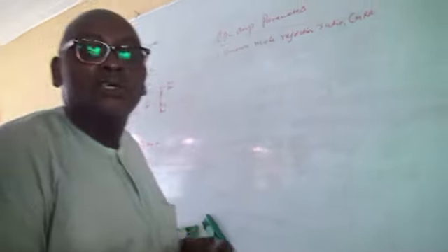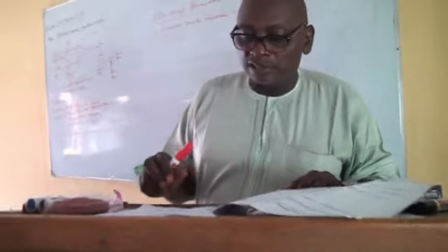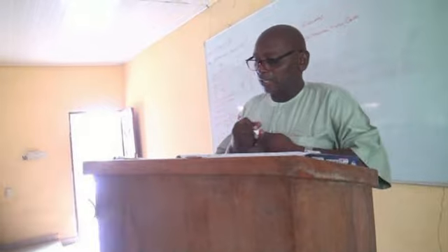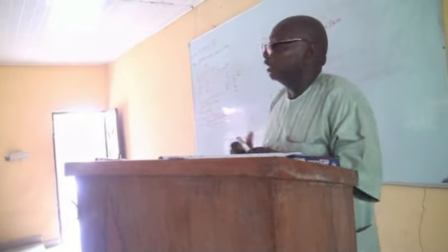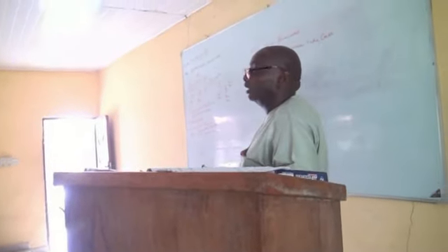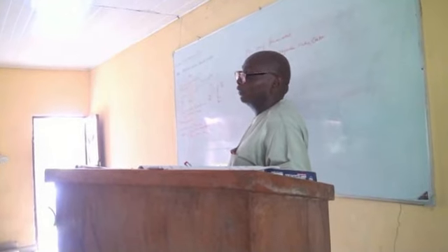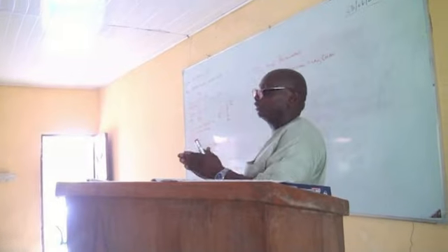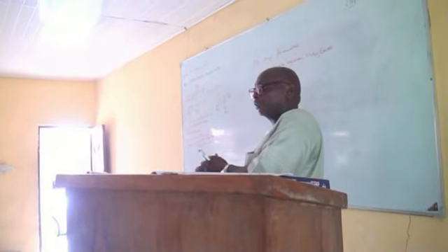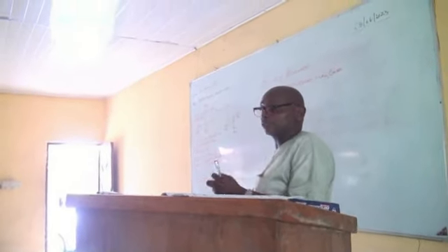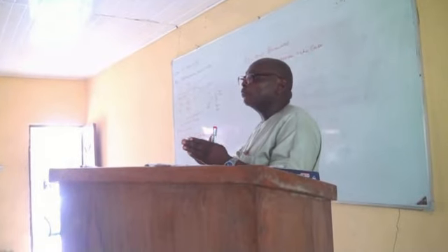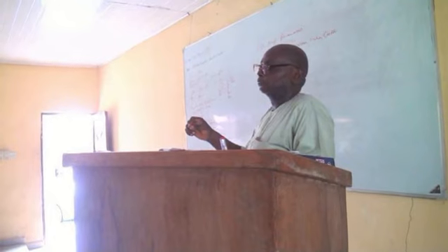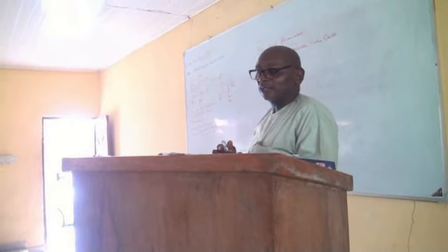Okay. Now, the second one we're going to look at is input bias current. Every op-amp has a differential amplifier at the input stage. I think I even drew the internal block diagram of an op-amp. I started with the differential amplifier input stage, then the voltage gain stage, and then the push-pull stage, right? So the differential amplifier is the first stage you encounter in an op-amp, and that stage affects the input bias.